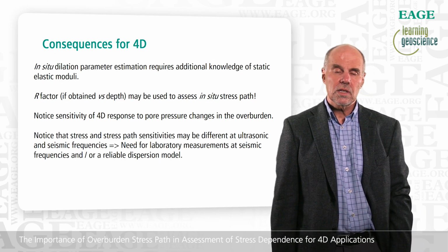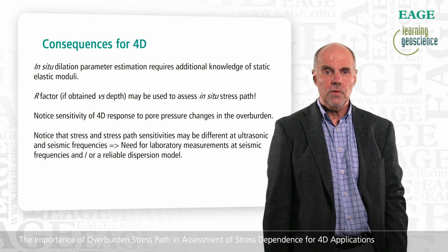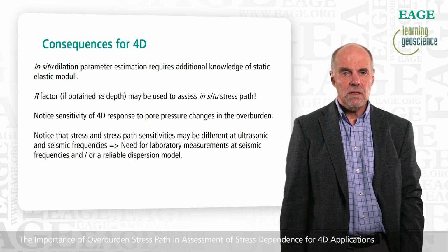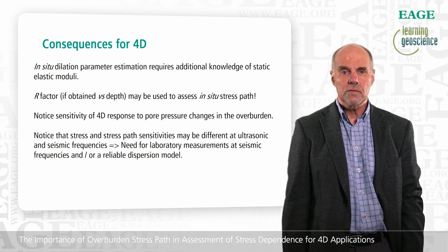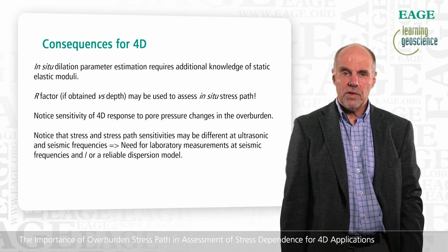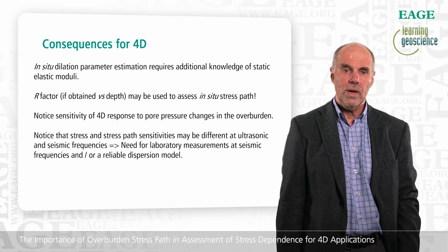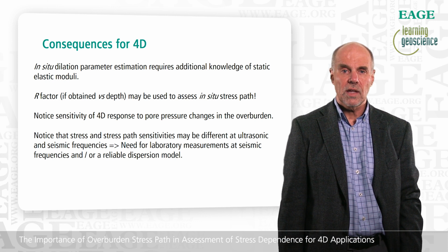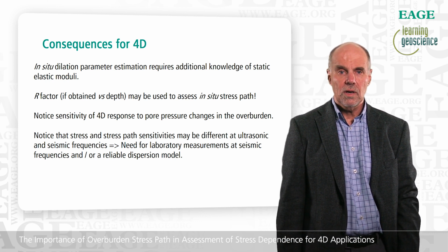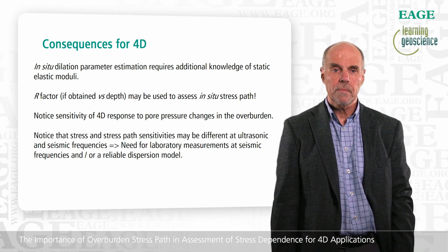One thing we should notice is the sensitivity of the 4D response to pore pressure changes in the overburden. We saw that through the influence of the Skempton parameters. It's quite often assumed that nothing happens with the pore pressure in the overburden because of the very low permeability of the shale. On the other hand, the very low permeability of the shale means that there is no chance for fluid to flow, at least not instantaneously, into the shale or out of the shale, and that means that the behavior is undrained, and undrained behavior implies pore pressure changes. And these pore pressure changes may have important operational aspects, for instance, with respect to drilling.